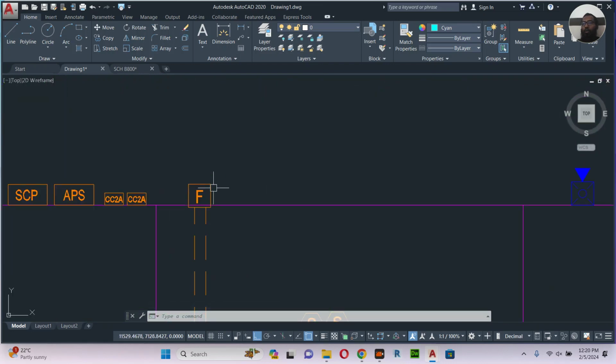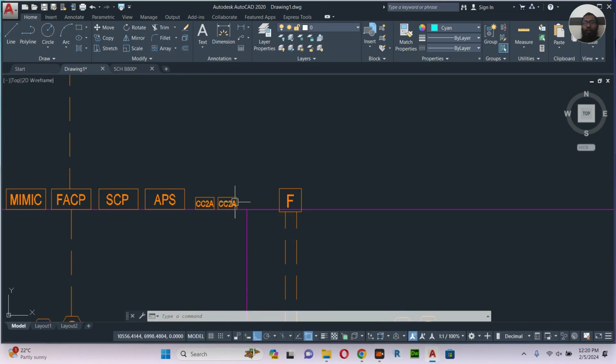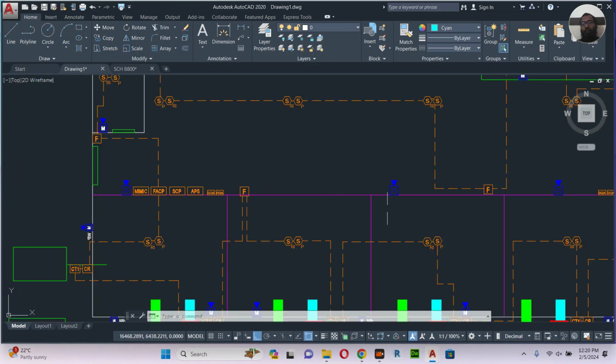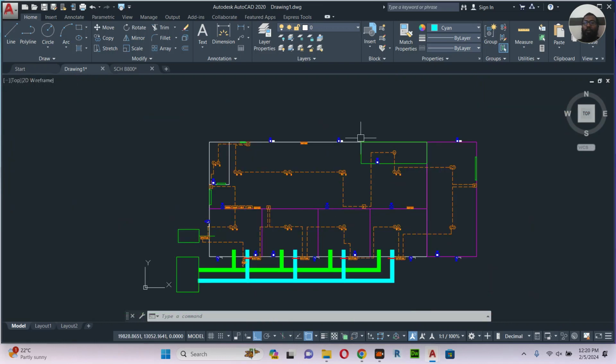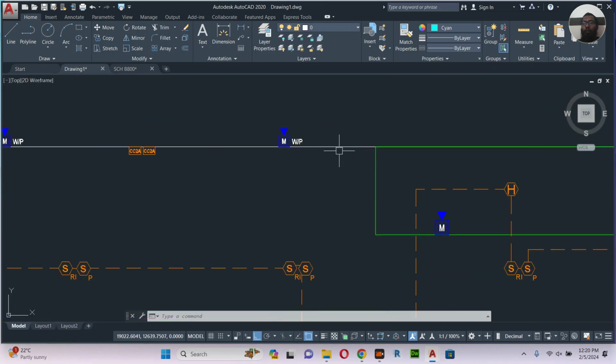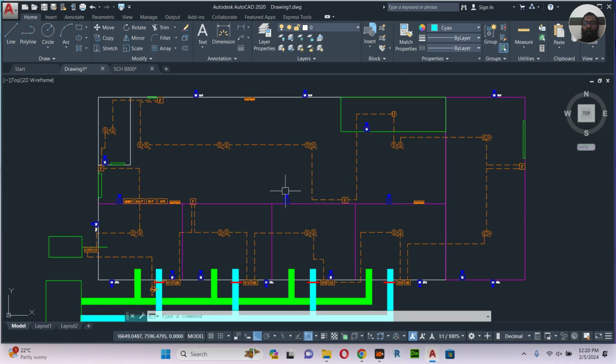The manual call point is 1250 mm from the FFL, like a switch height, the same height. And this module can be higher, more than 2 meters, 2.5 meters, it just depends. Even you can put an adjacent unit. And all the speakers are mostly above 2 meters, you can go 2.2 or 2.5, it depends. This is the installation height.